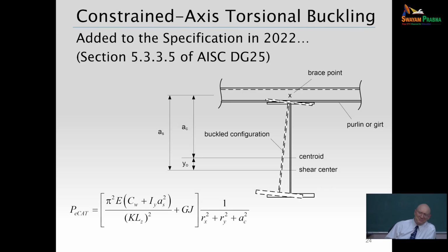And for example, as you said in your first example, if it is against the wall, where it is braced continuously, what will be that LTB? Right, we'll come back to that. Here it's not necessarily continuously braced if it's attached to framing members on the wall. If it's attached directly to a diaphragm, then yes, you could say that's continuously braced.